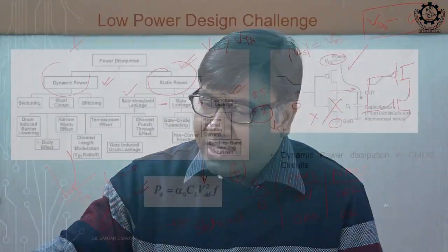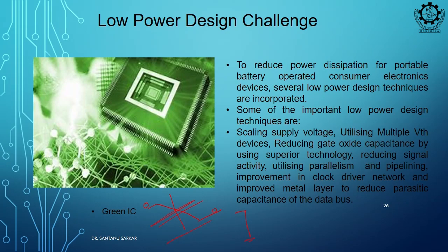Okay. So, as we are reducing, suppose you are working with 0.7 volt. Now, maybe dynamic power I am reducing, but leakage power is going up, and there are some other techniques that we are following which are causing leakage power to go up. So, now even design for low subthreshold leakage is getting important. Okay. So, this is the beauty of VLSI design, that it is so dynamic, and if you try to address one problem, another problem will come up.